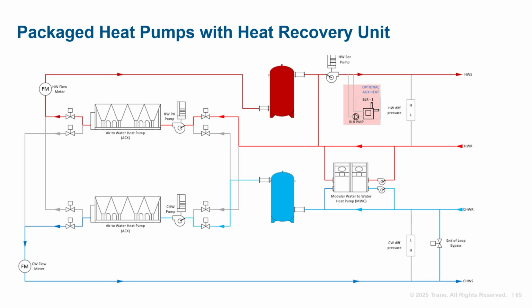In many cases, the heat recovery capacity is small compared to the system capacity because it's limited to the simultaneous heating and cooling load value. This system is likely to have a lower equipment cost, but the trade-off is that more controls design and engineering effort is required. Before wrapping up this section, let's recap the heat recovery and multi-pipe modular units.